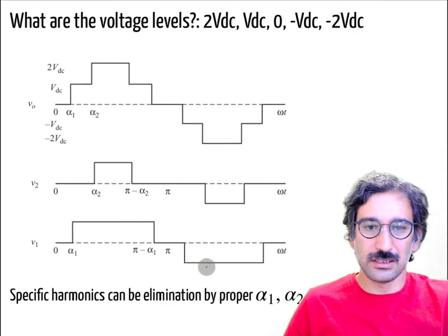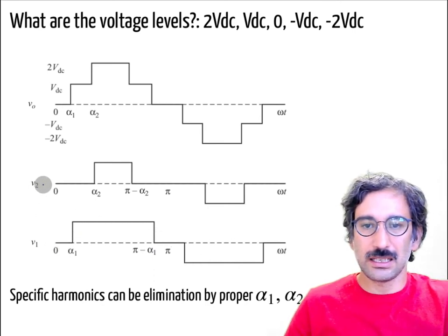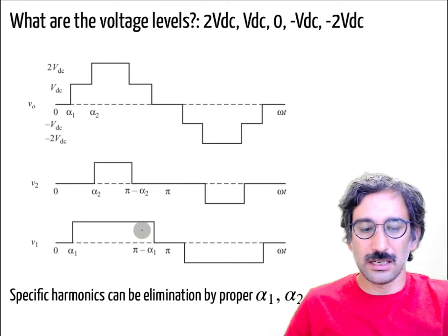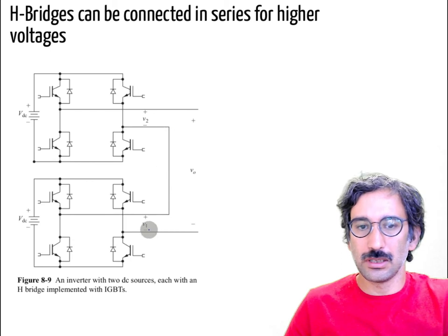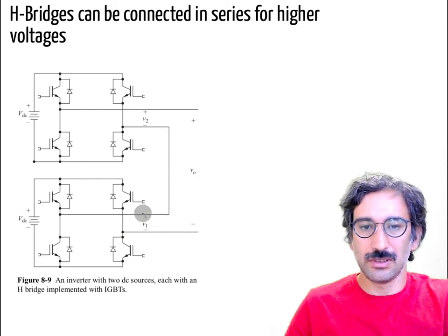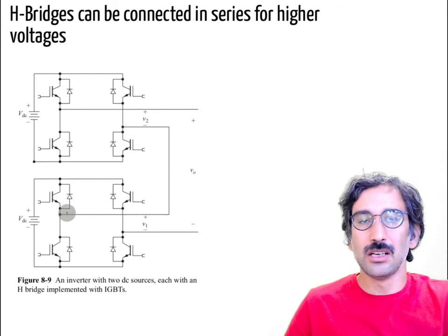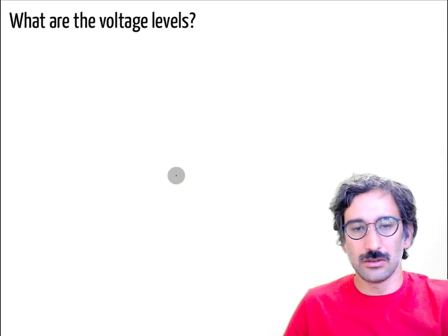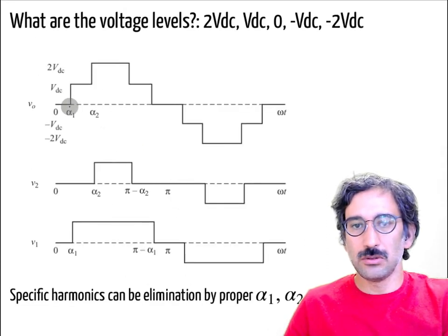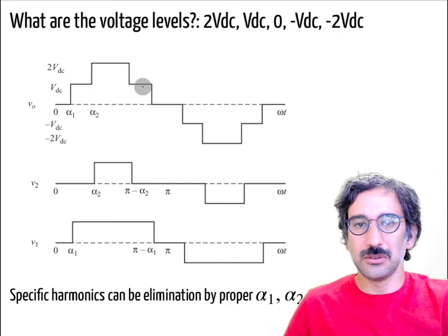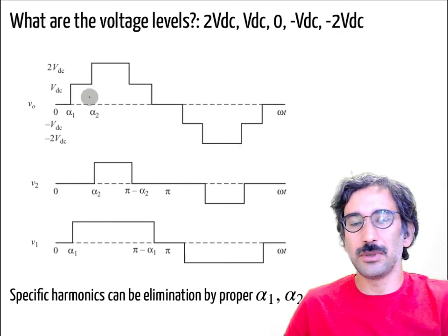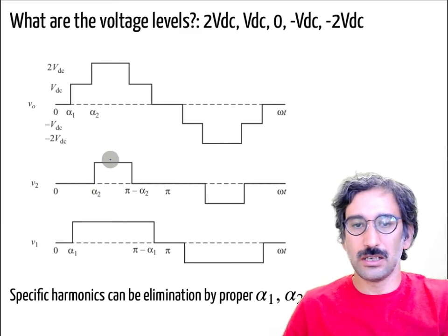And actually that can be the first voltage of the first H-bridge. So itself it is still working as a 3-level inverter, just one of them, and I can adjust the PWM of the other one. So once I combine these two, because V output is equal to V1 plus V2, they are connected in series, so the negative terminal of that one is connected to the positive terminal of the second inverter. So once I add these two, I can have that kind of waveform.